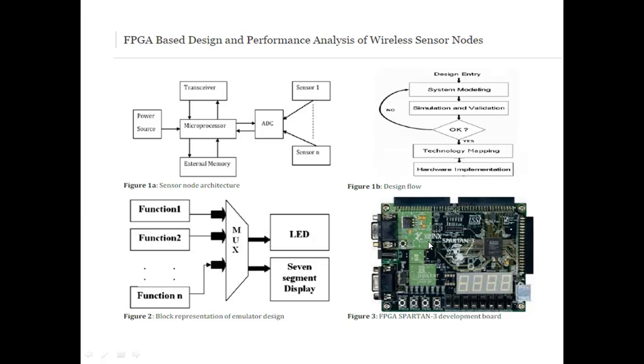The design flow is design entry, then system modeling, simulation and verification. If the simulation and validation is okay, then proceed to technology mapping, then hardware implementation. If not, then go again to design entry. It has been implemented with the FPGA Spartan 3 development board.